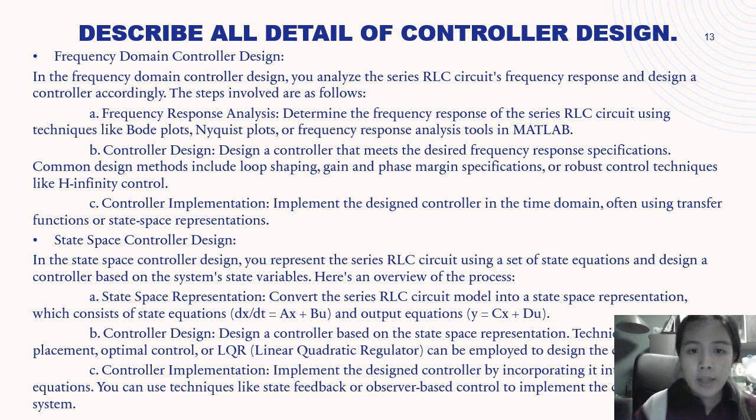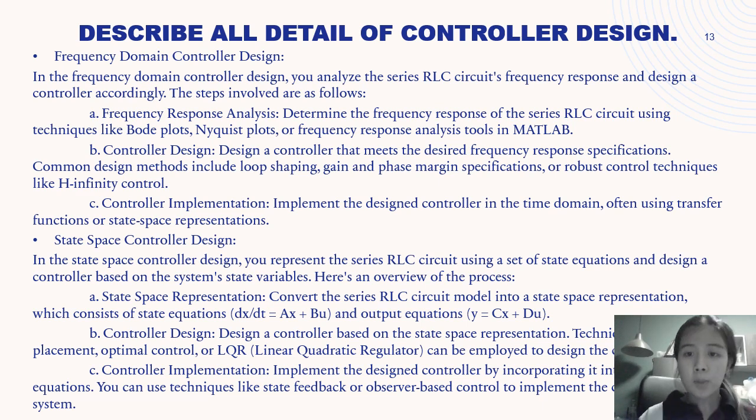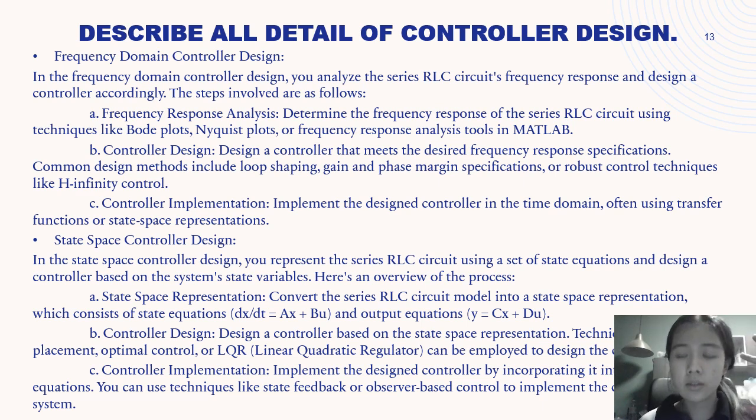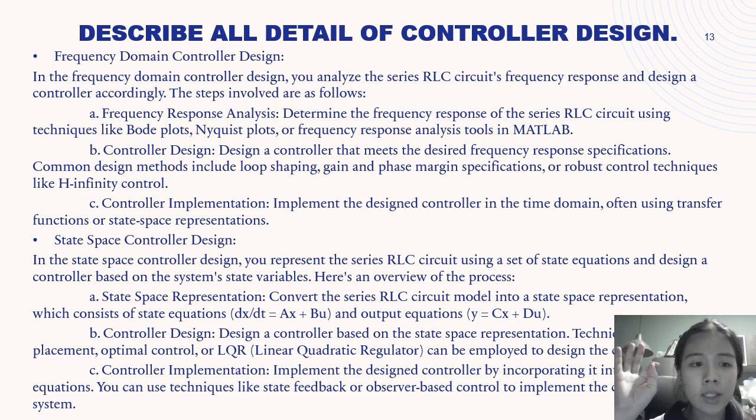Design a controller that meets the frequency response specifications. Common designs include loop shaping, phase margin specification, or robust control techniques like H infinity control. About the controller implementation, it is designed in the time domain, often using transfer function, state space representation, and the last one, state space control design.